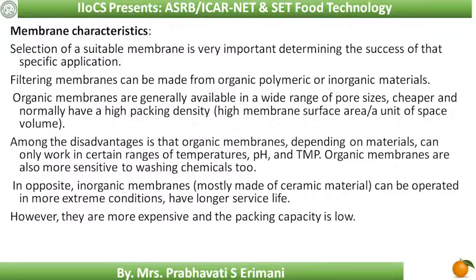Among the disadvantages of the organic membrane is that it depends on the materials. It can work only in certain ranges of temperature, pH and transmembrane pressure. So organic membranes are more sensitive to washing and chemicals also.